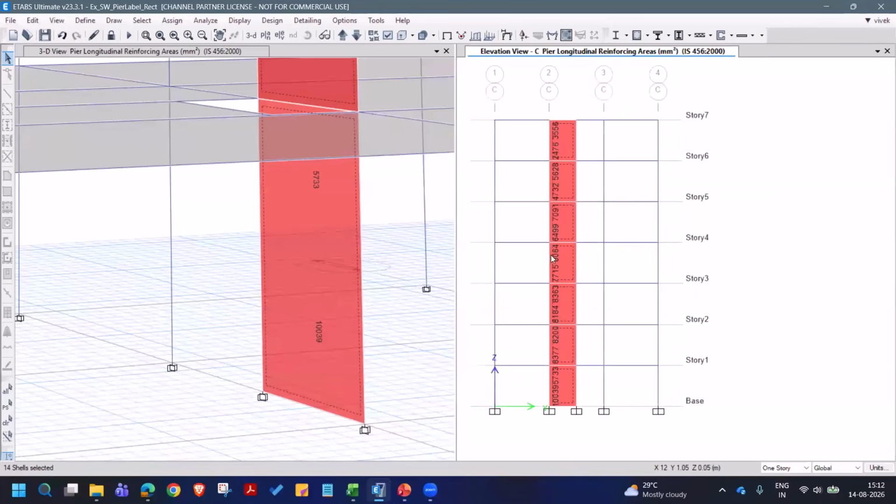Now there will be another question: how will we be doing this for all of this? So many hundreds of walls, or many wall elements, will be there. But typically, you should understand detailing is also a key thing in the shear wall design. How you detail the bar, just getting the reinforcement is not the end. You have to provide the reinforcement in the cross section, like more reinforcement in the boundary elements or confinement reinforcements you are adding to this.